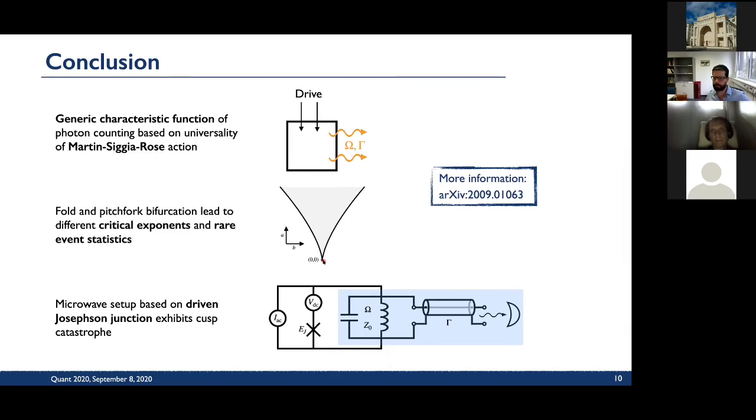So in our theory there's this alpha parameter, which is the impedance of this resonator. Our theory works if this alpha parameter is small, but once this parameter is small, there are of course only very few photons. So in the experiment, you actually want the alpha or the C naught to be rather large, such that you have a lot of quantum fluctuations. So you should build an oscillator where this characteristic impedance is close to the quantum impedance, but below, maybe a factor 10 below or something like that, such that you already get a signal before you should get a signal if you think about it in purely classical terms.